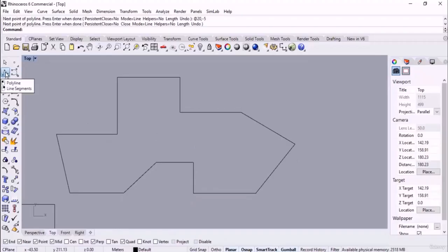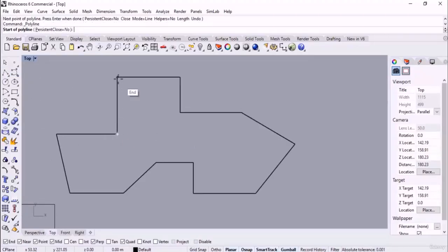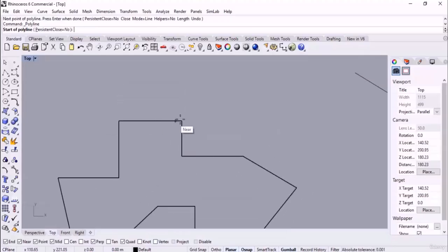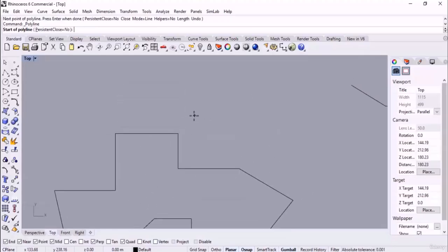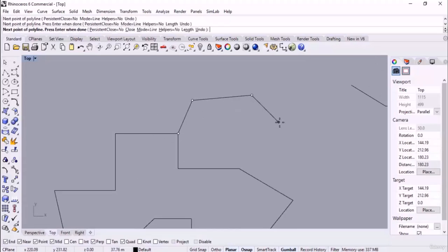Those who are masters in AutoCAD are already familiar with these. I pick line, and then I can specify the end points. A snap gives us some specific points from the line. They constrain the marker to an exact location on an object, like the end of the lines or the intersections, centers. For example, we're going to start sketching a line from the end of the line. So I click on the end, then I start sketching.